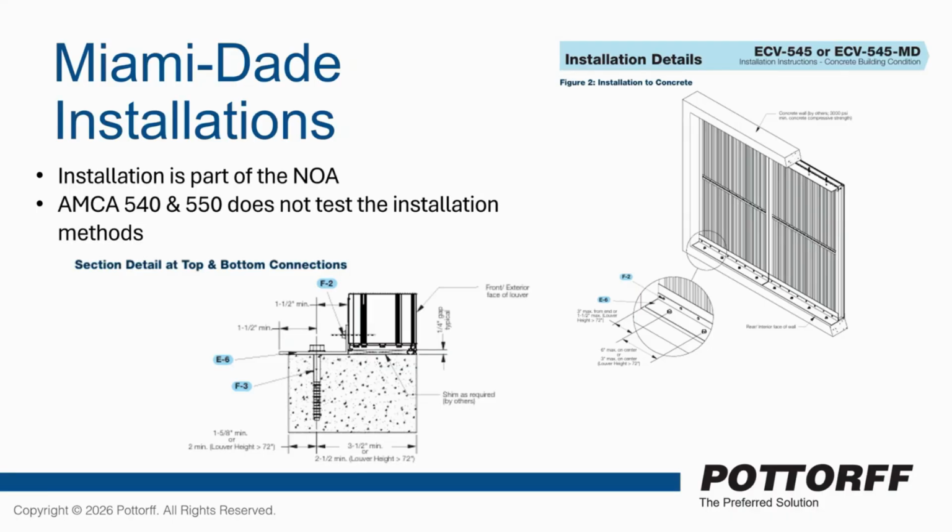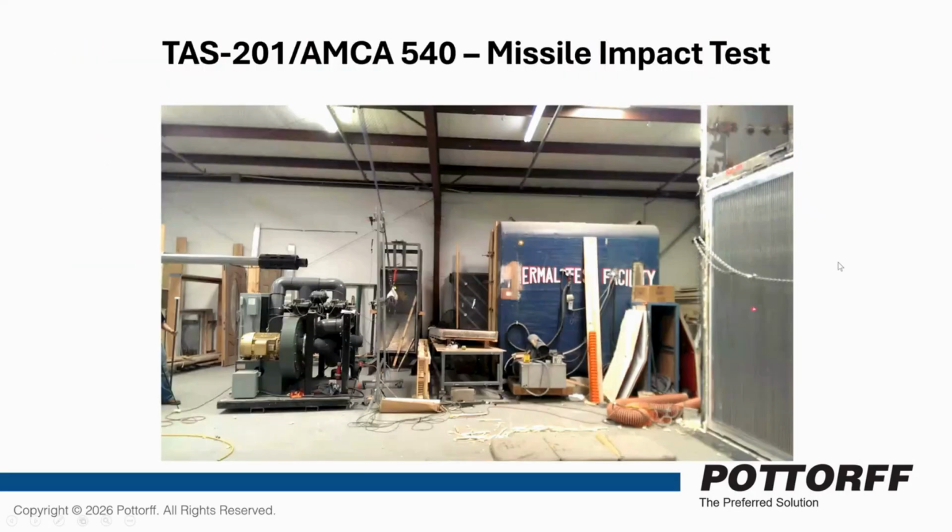We do not typically sell the anchors, but we will specify them if it is through Miami-Dade. To get the NOA, Miami-Dade will at least need to see that you have done calculations, maybe by a professional engineer, and have them stamped. And they will review those as well, depending on the building condition, they need to see some type of anchor being approved and at least shown to an installer.